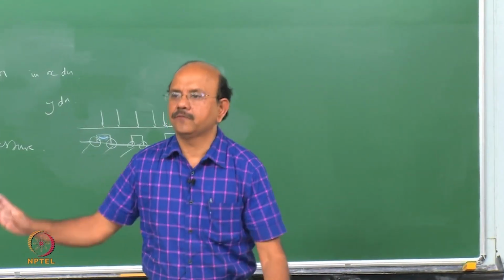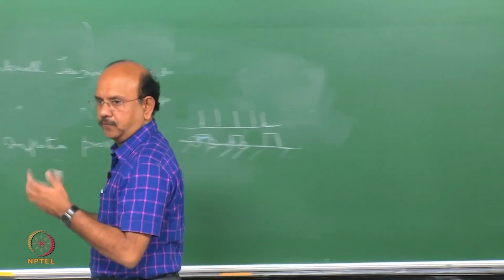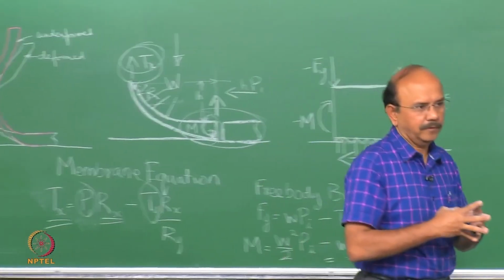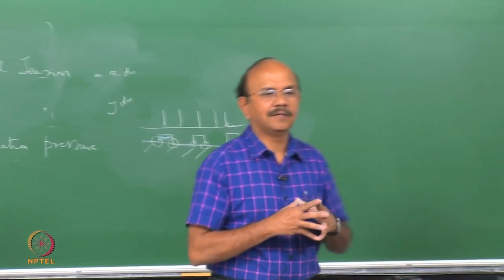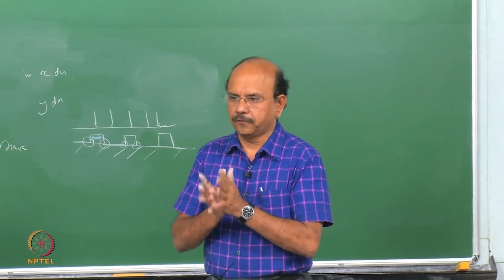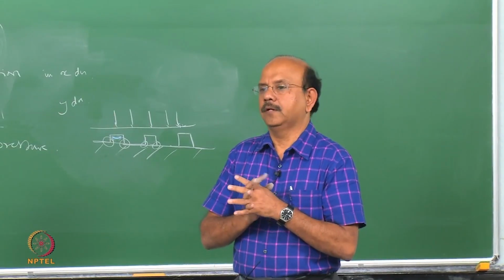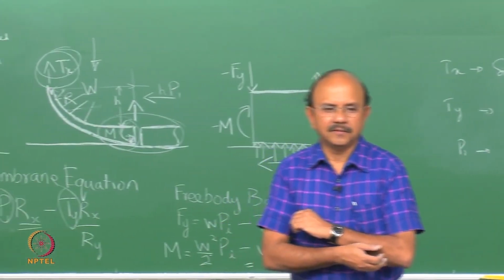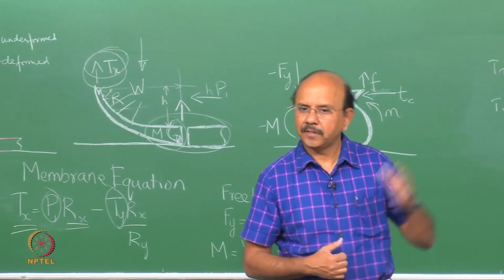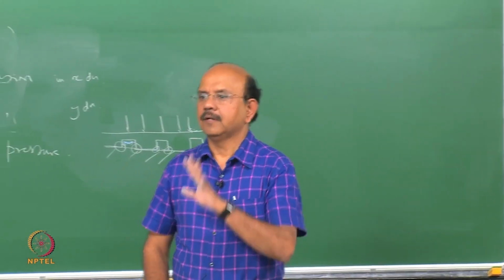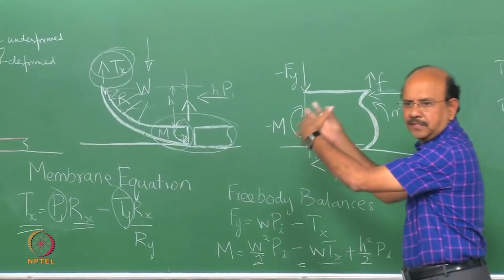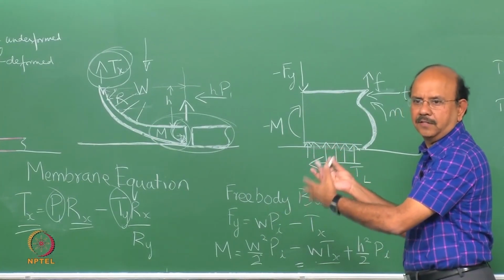In most of these analyses, we have left out centrifugal force, as the tire rotates. In some conditions, if you look at literature, centrifugal force becomes important, but under many conditions we neglect the centrifugal force because of rotation. You have to be careful. Usually in a truck tire, the centrifugal forces are not very important because of the speeds, but in passenger car tires, centrifugal forces become important. Right now we are not considering that, but then there will be other forces and some changes here.